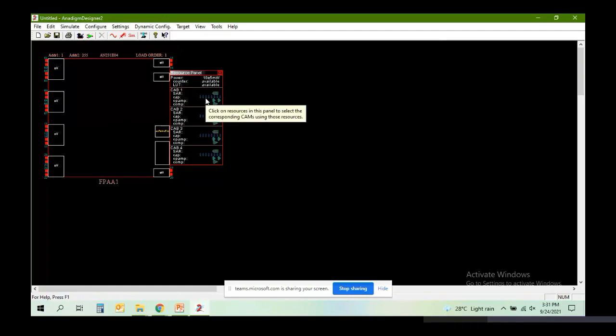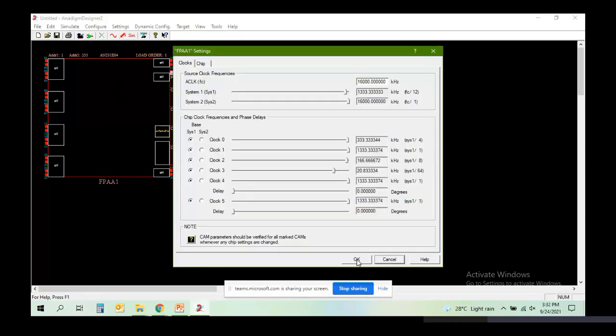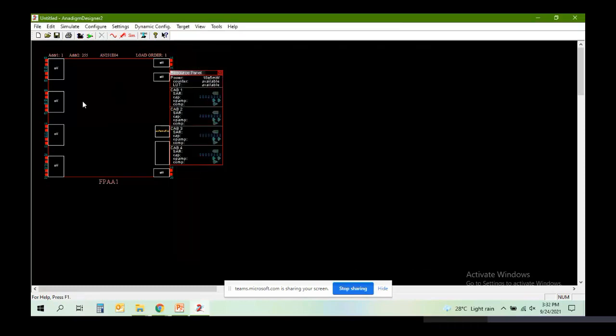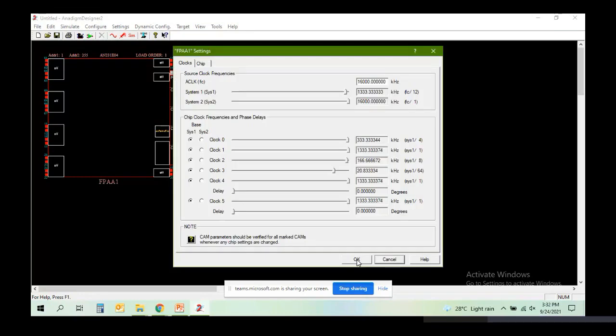I said three important things here. The FPAA is based on switched capacitor technology. Because capacitors can be programmable, when you want to dynamically configure your FPAA parameters, you can just control the switch. The capacitor will charge and discharge, so we can dynamically program the FPAAs. Another is that a switched capacitor needs a clock signal. You can double click inside the FPAA and change the clock settings based on your system and application demands.